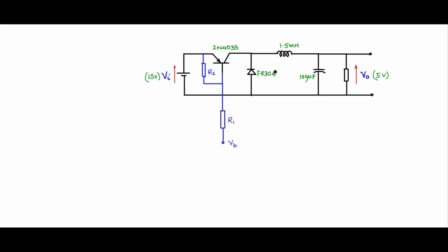You are having almost all the components. And for I0, you can design I0 in 5 milliamps to vary between 5 milliamps and 500 milliamps. Max is 500 milliamps. So the resistance here is known. Now what do we connect here? And then at what frequency do you switch this BJT? So let us put that down. Switching frequency of the BJT is 20 kilohertz.